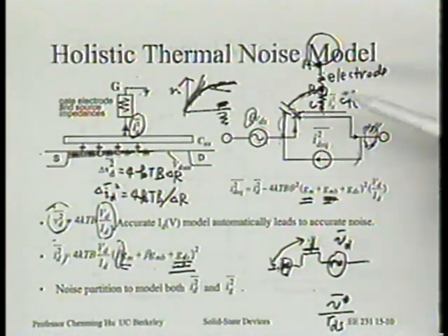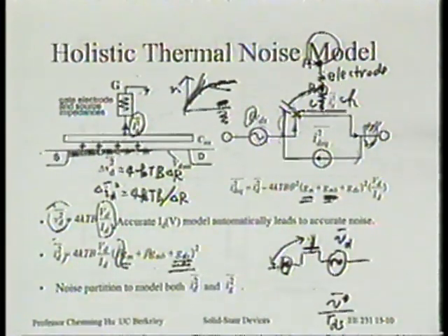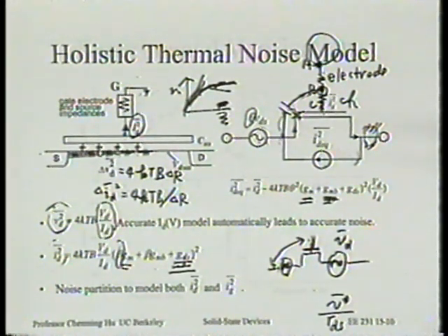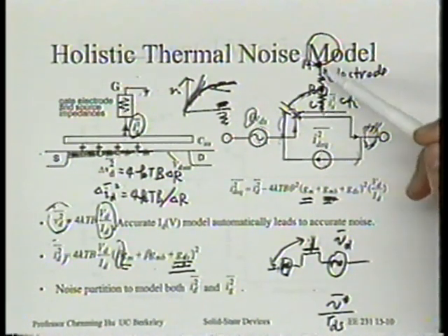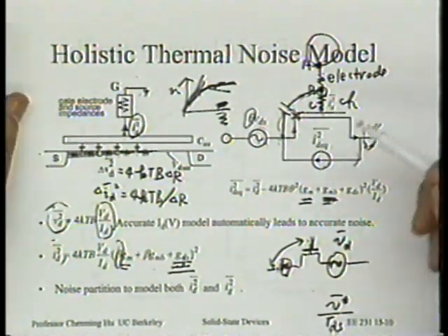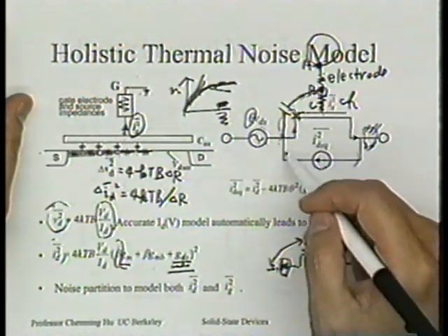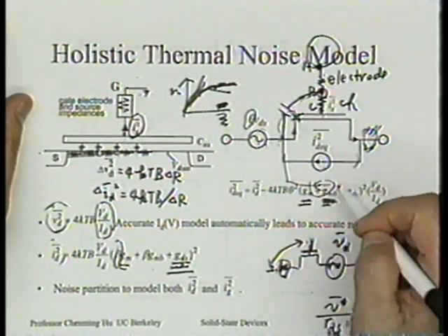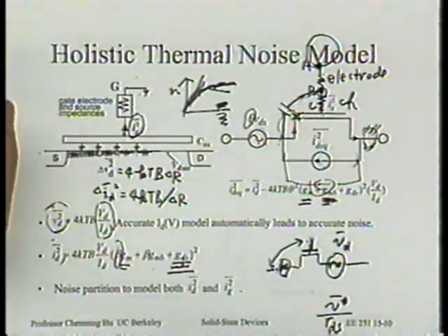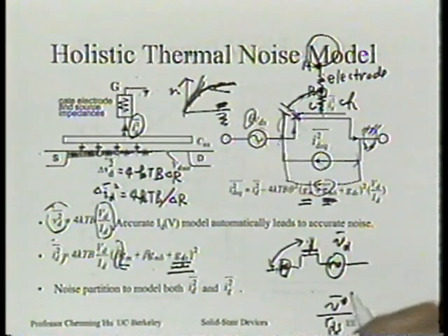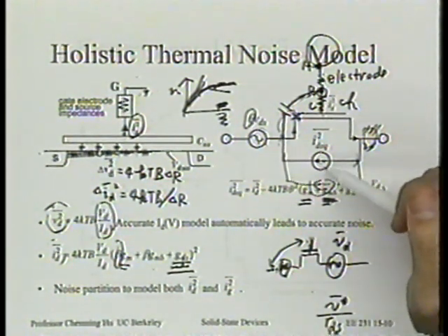So automatically we want the SPICE engine to take care of that coherence. You see that? Right? And automatically the coherence is taken care of by the SPICE engine. If you put in two separate current sources, as people tried to do in the past, now you're going to have to figure out how to handle the coherence. And in fact, SPICE never adds things in a coherent manner.